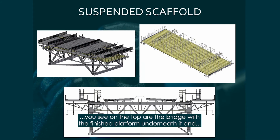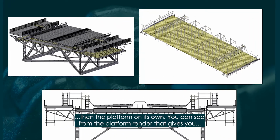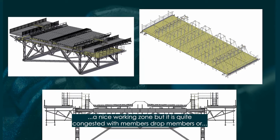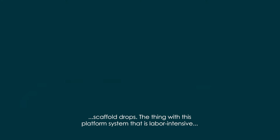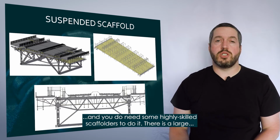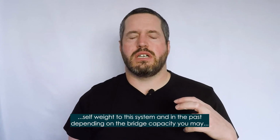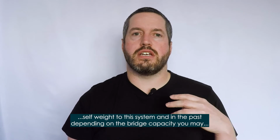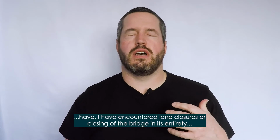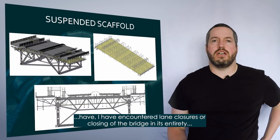So the other two images you see on the top are the bridge with the finished platform underneath it, and then the platform on its own. You can see from the platform render that it gives you a nice working zone, but it is quite congested with members, drop members or scaffold drops. The thing with this platform system is that it is labor intensive, and you do need some highly skilled scaffolders to do it. There is a large self weight to this system, and in the past, depending on the bridge capacity, I have encountered lane closures or closing of the bridge in its entirety.